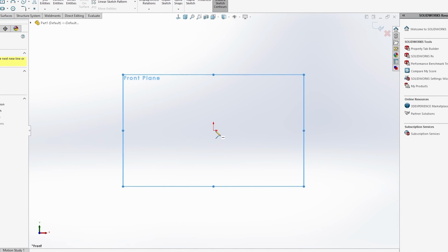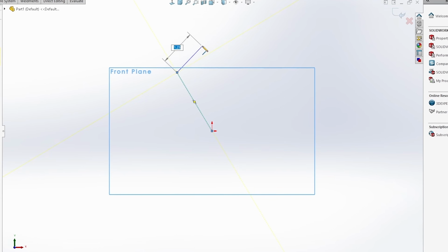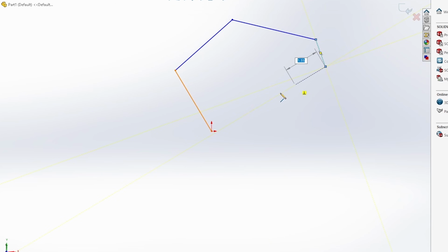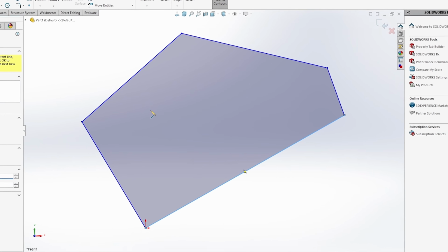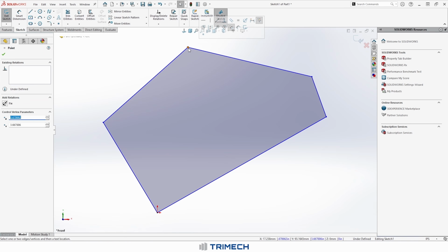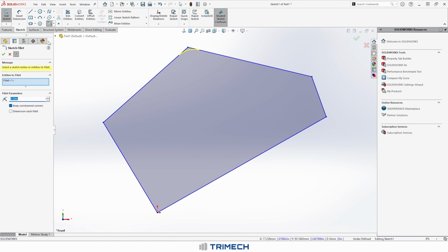We're going to deliberately sketch something up real quick that's not going to use any sort of perpendicularity, just to showcase what virtual sharps can be used for. Let's throw in some radii on some of these. We'll go with something like a 1/2 inch. We don't want to do that, so we can hop out. Let's grab that corner. Do our radii that way. And we can accept that.